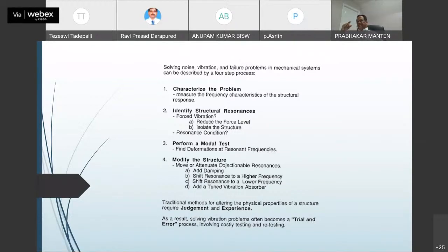Under a resonant condition, the secondary mass, which is smaller and has a less stiff spring than the other one, will absorb the energy, and essentially it will become a 2 degree of freedom system with two modes which are swept away. If you look at that analysis, it will show the two modes moved away from the resonant condition, and so resonance does not take place.